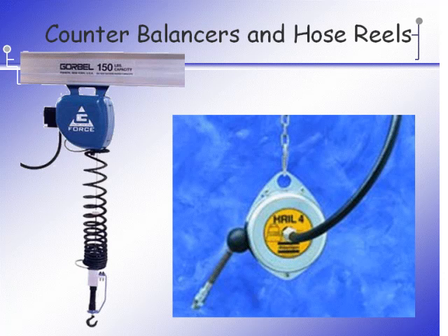Some other ways that you can counterbalance tools is to do it with your hose reels, so you get your reels off the floor as well. And that's great to keep your hoses from getting damaged from being on the floor. It eliminates your tripping hazards, as well as helps to counterbalance the tool.